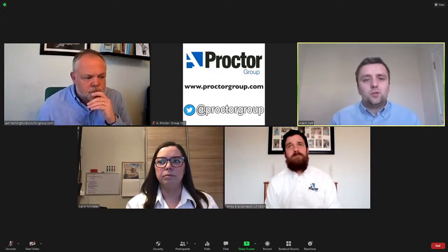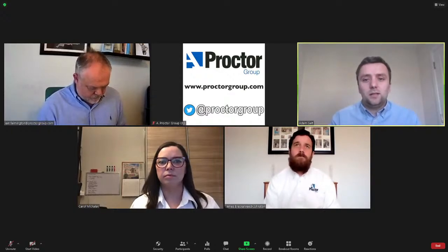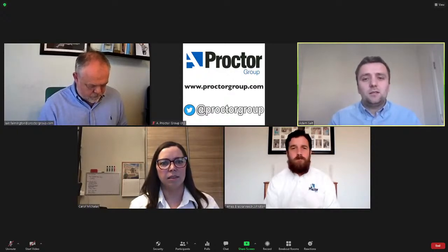First of all, I'd say, what's your type of property? Is it old with lots of unique features that you don't want covered up, particularly properties in Bath, for example, like the case study in the webinar? The property could also be listed, and then planning wouldn't allow it to go externally. So in those situations, we'll be looking for internal insulation, ideally. And if these features don't apply to your property, then we're going to be looking at external options, because then we're reducing thermal bridging. So externally is ideal from a design point of view, but in some cases we can't.